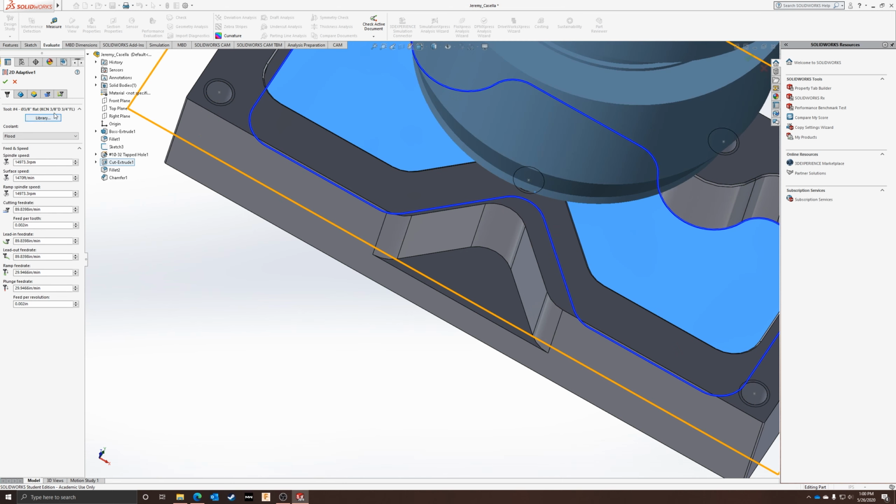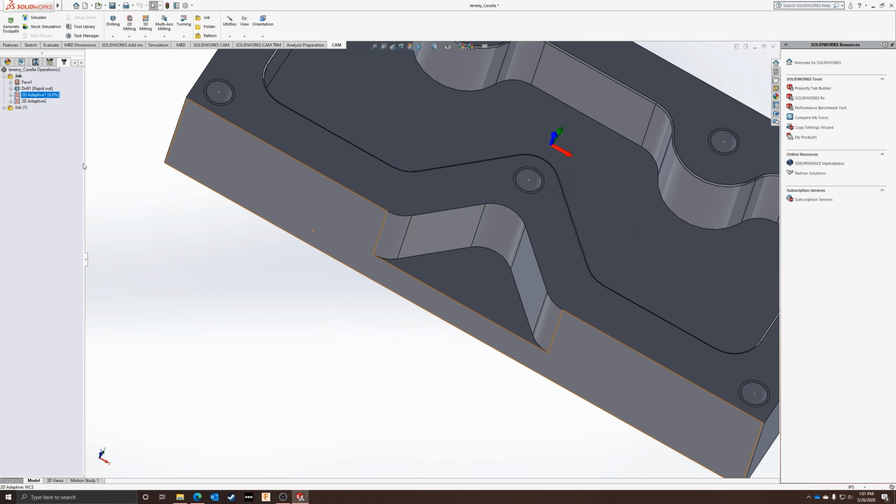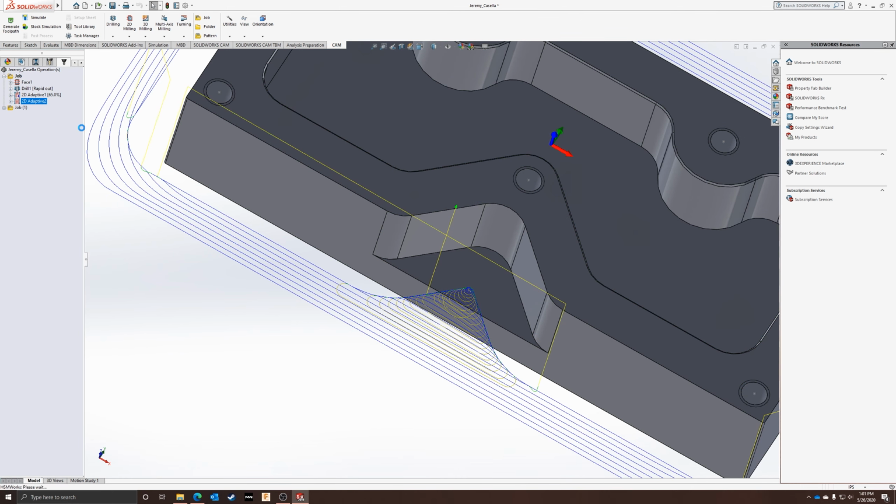So I look at my tool, it says 3/4 flute length. So once again, it's 0.9 times 0.75, done. This is still below that. We'll make it 0.015 for fun, just something reasonably below and not too small, nothing smaller than 0.01, but still smaller than the proper engagement. And then I click back. Done, it's fixed. Do the same for the outside, right?